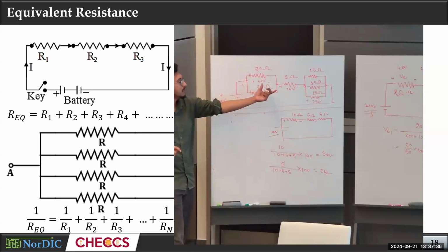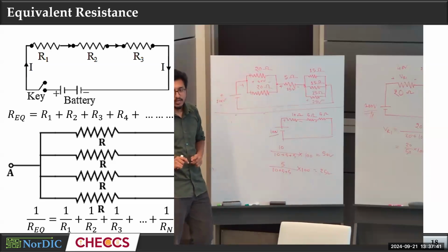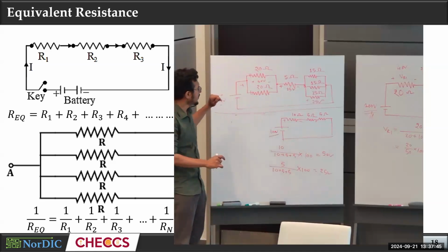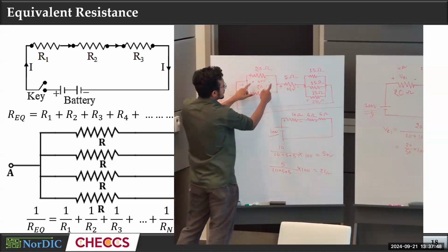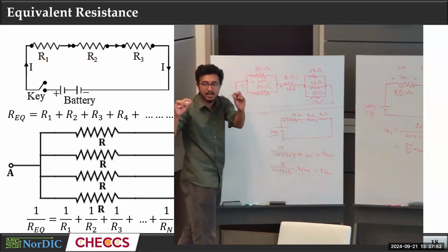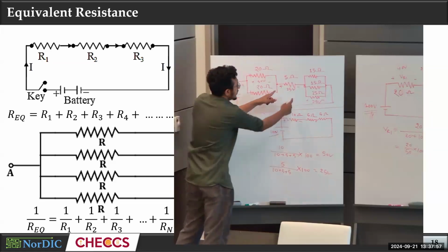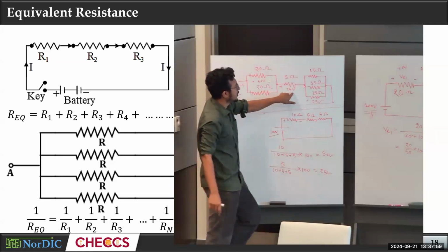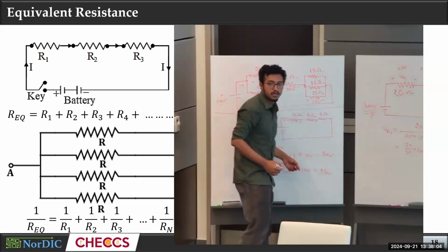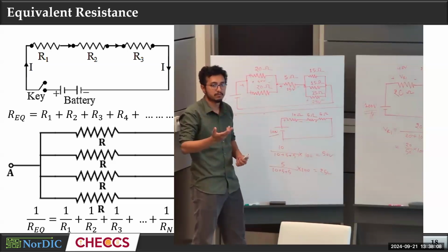Now at this stage you have everything. You can tell the voltage difference across each of the resistors. What is the voltage across this resistor? 50 volt. What is the voltage across this resistor? Same. They are connected in parallel. If they are connected in parallel, they have the same voltage, right? Here as well, they have the same 25 volt. These three all have how much voltage across them? 25 volt.